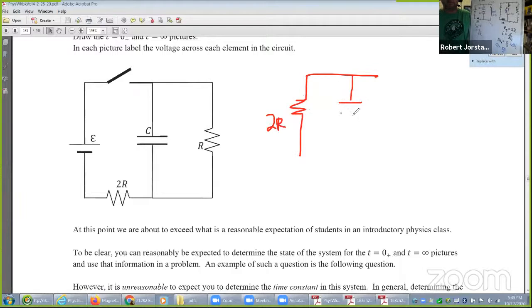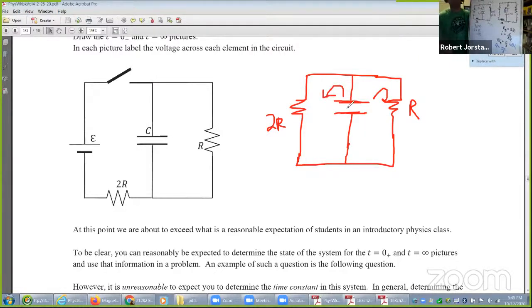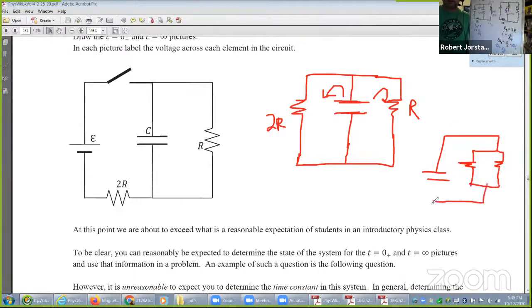C and R. And if you ignore the battery, which is just a constant added to the differential calculus, we could say that, oh, isn't this capacitor basically working through this resistor and that resistor in parallel? And it is. And so you could say, from the capacitor's perspective, it's the same thing as this: 2R and R.